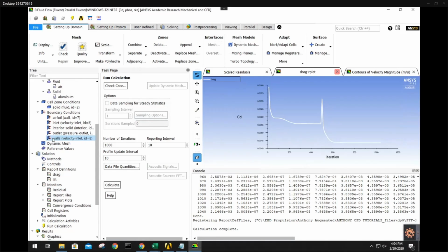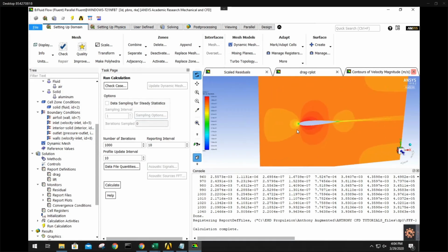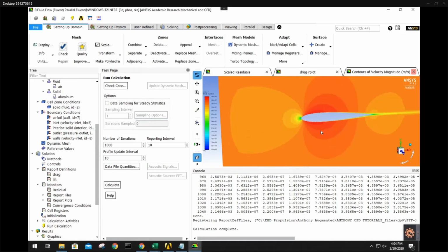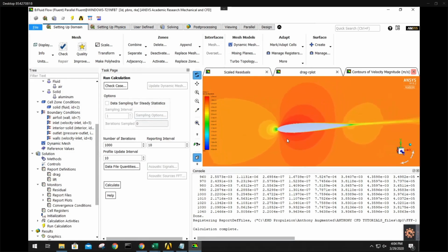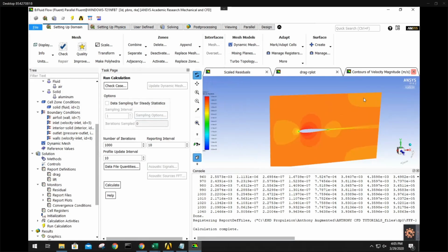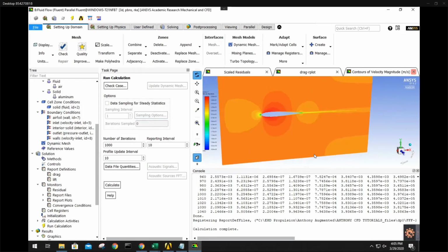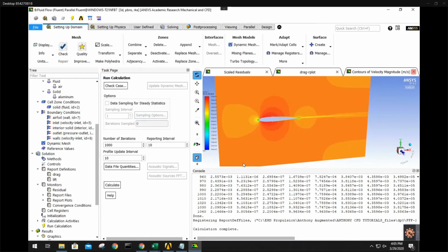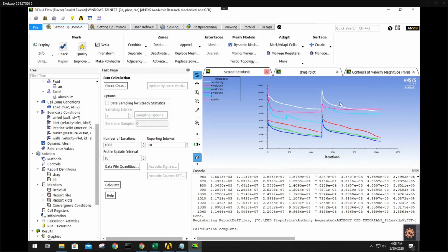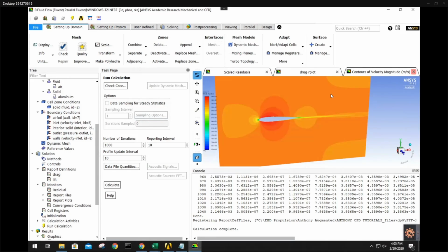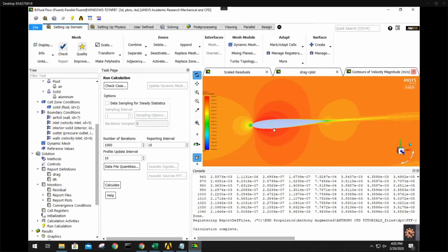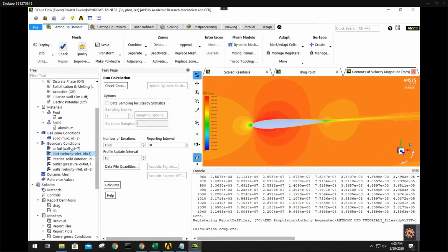To show this more, I want to start doing, and so if I look at my contour too, close to the airfoil, this looks pretty decent, to be honest. This stuff should not be a different color. That's probably due to convergence, and it probably will go away eventually if I let it run more. Like you can see, it has room to go more down, but overall this actually looks kind of decent. So I'm gonna change the inlet.